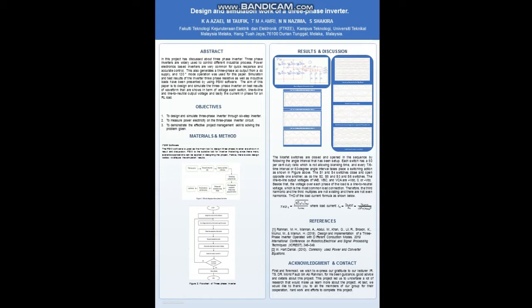In this paper, we are using a 120-degree mode operation, and a simulation and test result of the inverter with 3-phase resistive as well as inductive load has been presented using PSIM software. The aim of this paper is to design and simulate the 3-phase inverter. The test result waveforms are shown in terms of voltage across each switch, line-to-line and line-to-neutral output voltage, and lastly the current in phase for an RL load.